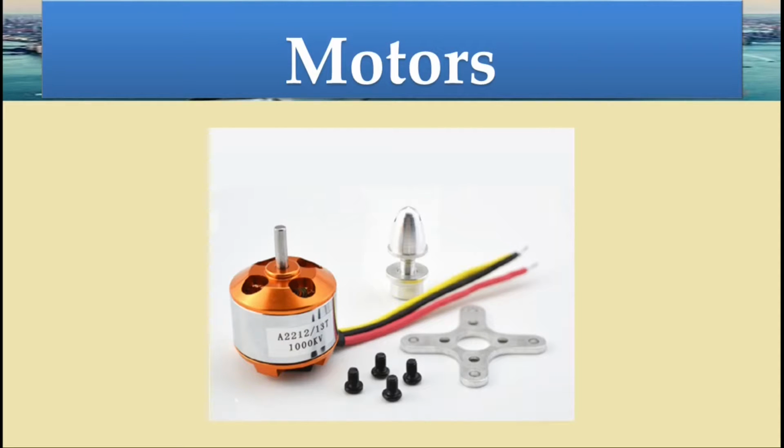This is very commonly used in every drone. As you can see, there is kV rating on each drone motor. For the bigger drones, less kV is used, and for the smaller drones, high kV rating is used. As the size and weight of drone increase, the kV in the motor will decrease. As the kV rate decreases, the propeller size is increased.